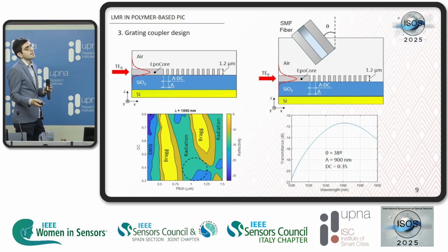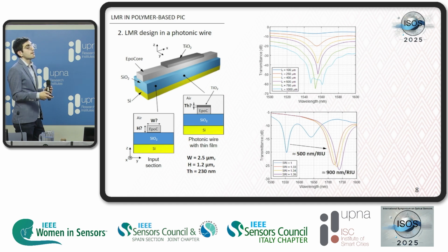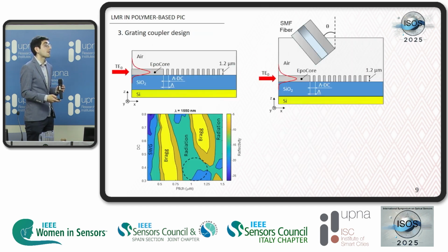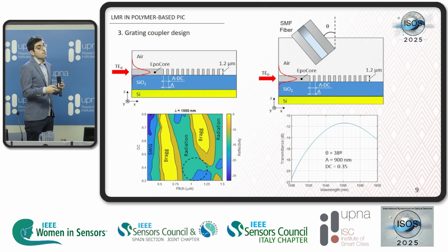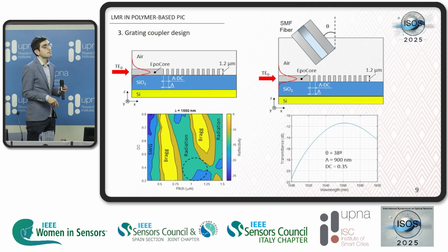This bandwidth is typical of a grating coupler. It's difficult to obtain grating couplers with a wider bandwidth. This means that this experiment is not possible in reality. We would have to either design several devices with different grating couplers with different bandwidths, because we are not going to be able to cover all this bandwidth with a single grating coupler, or another option: this curve for this grating coupler corresponds to this fiber angle. If you start changing this fiber angle, the grating coupler curve starts to shift in wavelength. It also can go down, so maybe it wouldn't be a good solution either, but sometimes it's used.